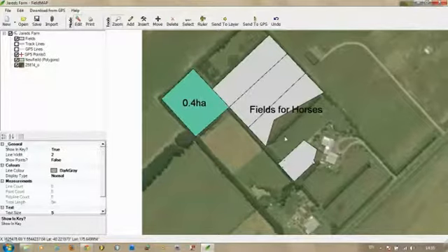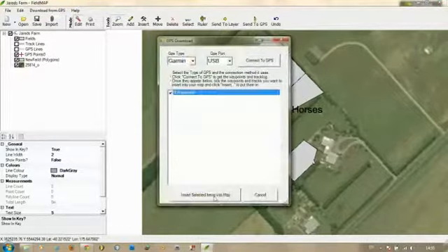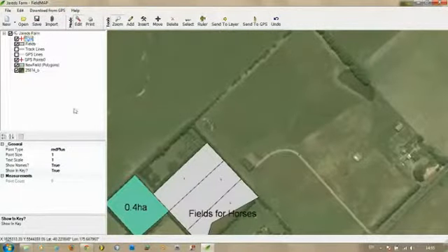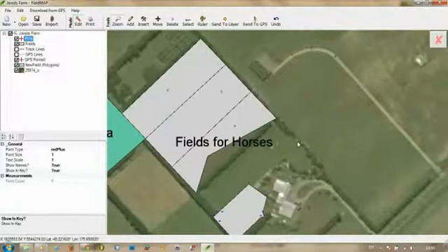If you choose to elect the GPS method, you will need to clear the GPS memory, which is explained in an earlier tutorial, and then go out to the field and collect the relevant waypoints. After downloading the new data from your GPS, you can use the polygon tool to mark out buildings, etc., the polyline tool to show creeks, roads and tracks, etc., and points such as troughs and power poles, etc.